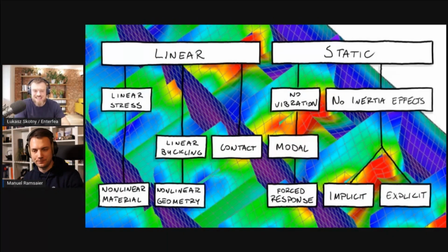And the only realistic outcome you will get is a single number, a single digit called eigenvalue. That would be like critical load multiplier to those of you who used Eurocode terminology. The idea is you applied load, and this number tells you what would be the multiplier for this load to reach failure.